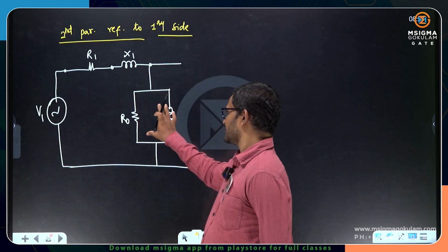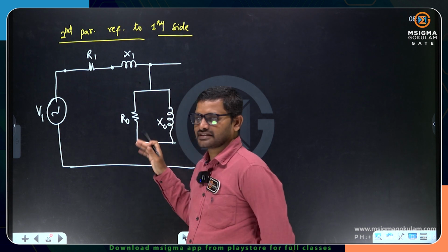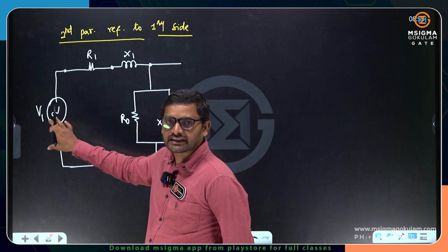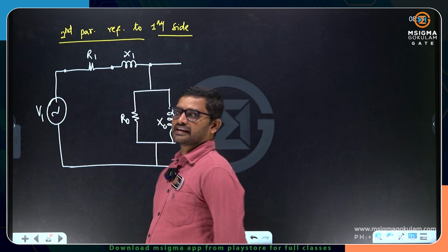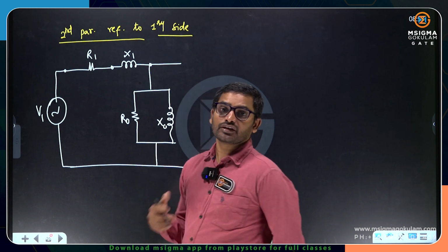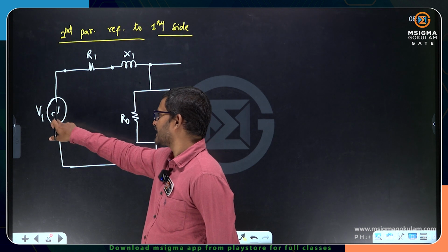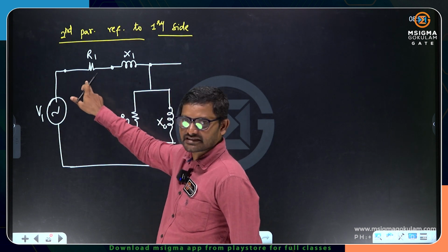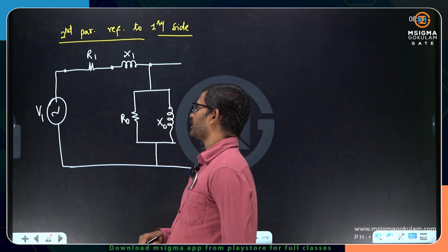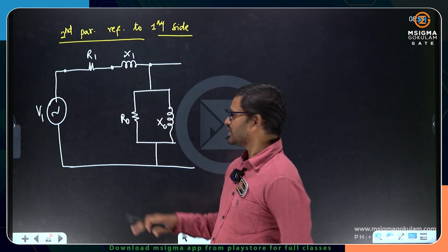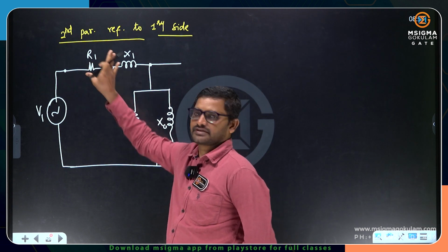So if one winding is energized, the source can see the winding parameters, and also can see the core branch impedance. The voltage source gets an opposition due to winding resistance and also core impedance. So that's why these parameters are drawn. Not under no load condition. Under no load condition we draw only this one, because we neglect the drops.